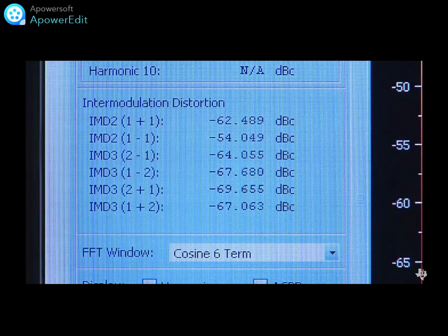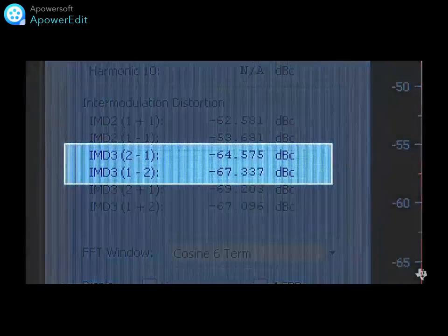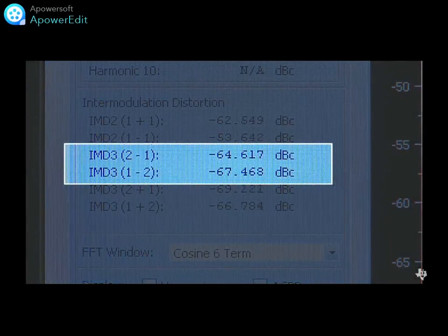Now that we've considered the lower end of the base station RF spectrum, it's more interesting to consider the high end at 2.7 GHz. So let's look at the performance with two input tones around that frequency. At 2.7 GHz, traditional base station ADCs don't even operate. However, this RF sampling ADC maintains excellent performance out to 2.7 GHz, yielding negative 64 dBc at 3600 megasamples per second.